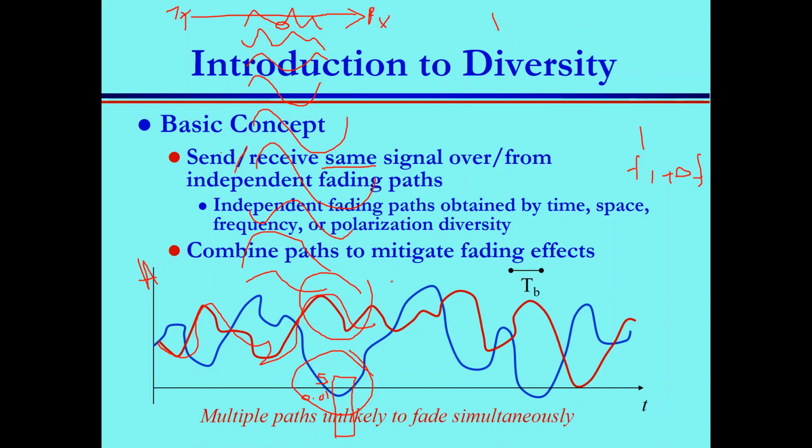But this is not guaranteed diversity. It's statistical. Depends. Sometimes you might get two bad channels. You send it from two paths, but still you are getting bad performance instantaneously, I'm saying. But statistically, when you get all the random values and average all of them, you must get some improvement. And usually we measure the performance of wireless channels statistically.